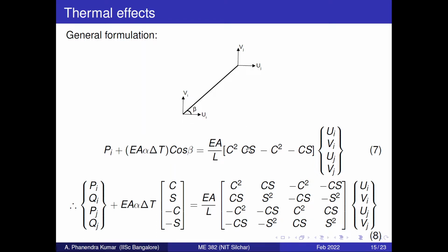We have already represented this part in the stiffness matrix. If you refer to the stiffness matrix in your notes, you can see this is the first row in our stiffness matrix. So this first row and the multiplication of degrees of freedom gives the load at the ith node, or the first degree of freedom point. So that is the force. So this total force should be equal to this force. Then it will be in equilibrium.